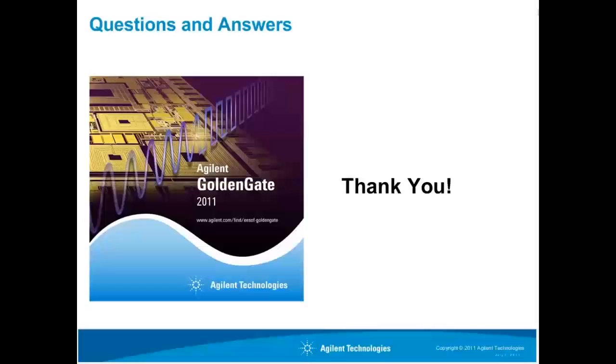So you can execute dynamic measurements on SystemVue simulations using the 89600, and you can use the fast circuit envelope model as part of one of those simulations. So you can use the 89600 to demodulate a signal that's passing through a fast circuit envelope model, so you can monitor any distortion, EVM degradation type effects.